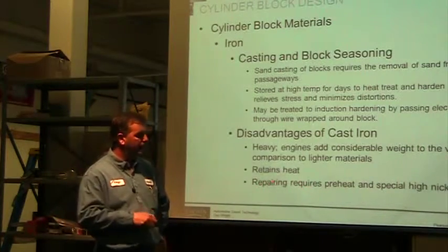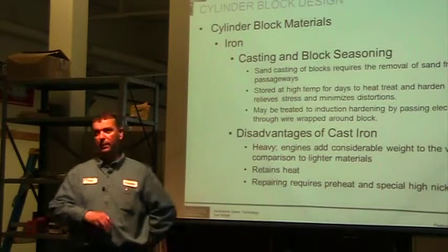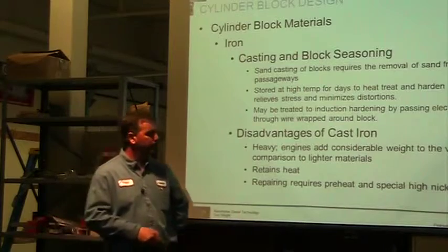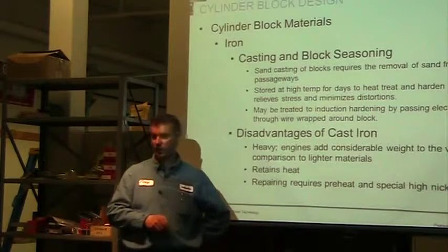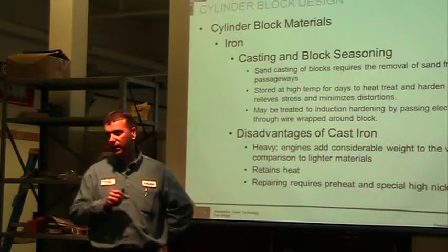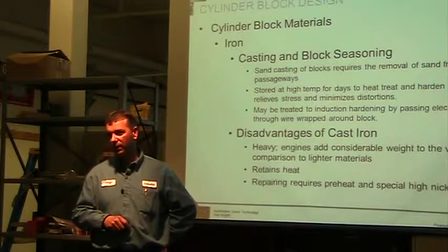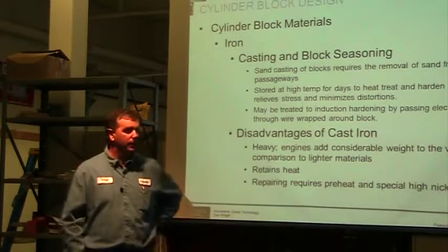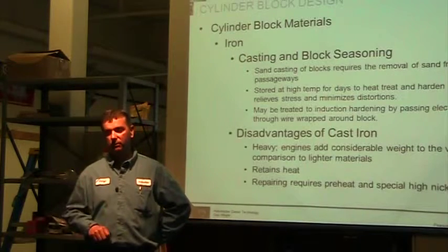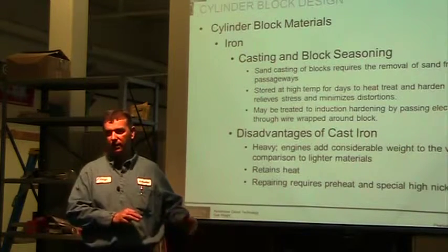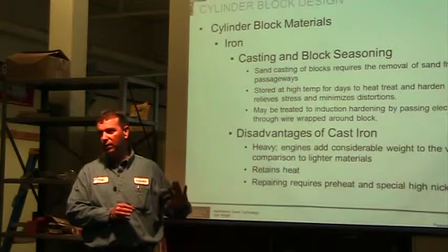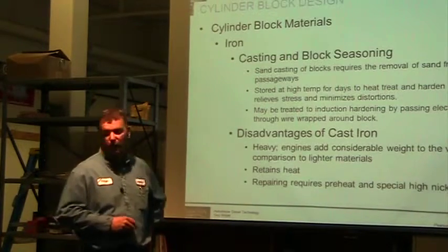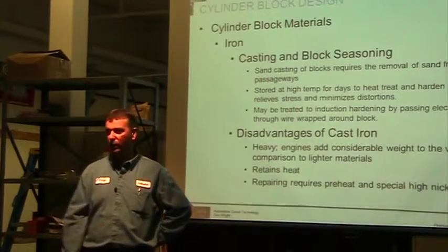Repair, we talked about that. You have to preheat it. You got to preheat the whole block, get it all nice and hot. It's got to stay pretty hot. You have to use a special rod. It's got to have lots of nickel in it. You can weld it, and then you want it to cool real slow. You definitely don't want to be throwing water on it. When you're done welding, you just put it someplace and let it cool; the cooler and slower that it cools, the better off you are. So you better know what you're doing if you're going to weld cast iron.